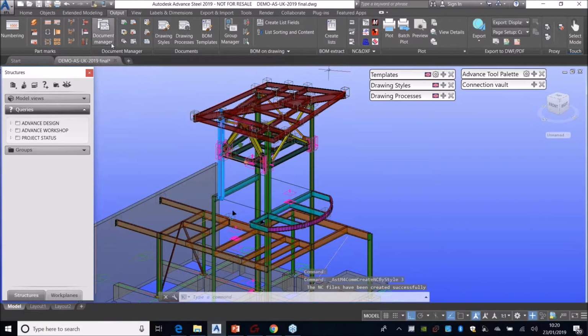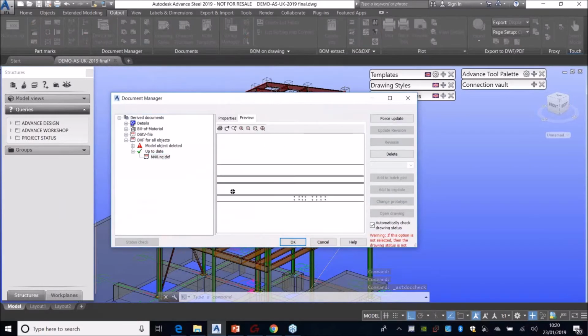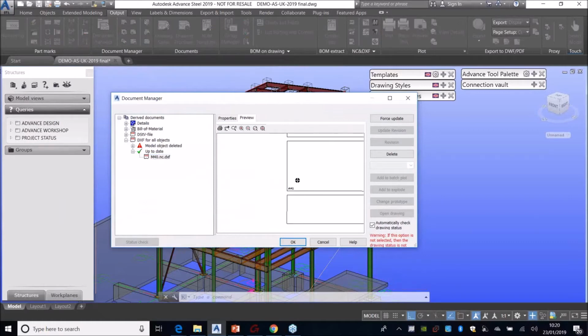Now, if we output the DXF of this profile again, here, of course, we'll have M40. Now, why they wouldn't want this is because, of course, to coordinate the fabrication in the shop, you'd want to still see the assembly mark reference tagged to one of the items. Maybe not all plates, but you would still want to see it on the main profile of the assembly, which the jig in the shop is going to be based around. Jig might be a North American term. I hope it's not. But whatever they use, the table to weld the other components together.